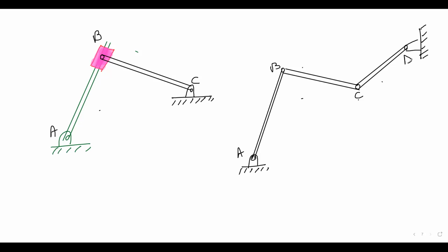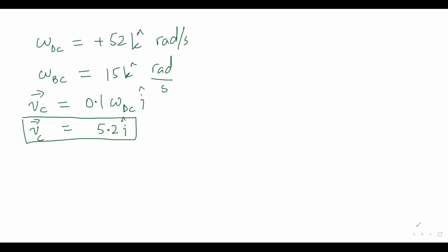So one thing I would like to ask you is, at this moment, at the pink position, the velocity of B, let's say, is going in this direction, upward. Then I have an angle, so I will resolve it and take the X and Y components separately. Also, we choose the small XYZ coordinate the same as the general reference frame because we are trying to make our computations easier. I always take the same as capital XYZ to make my life easy.